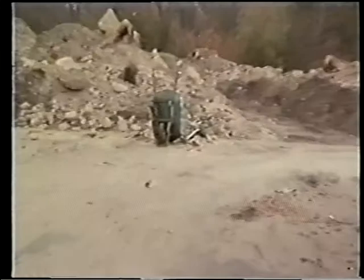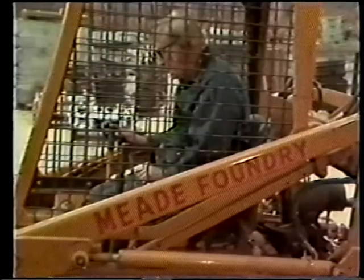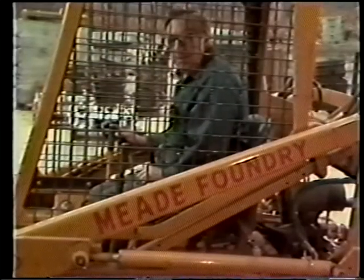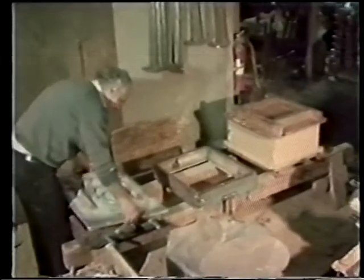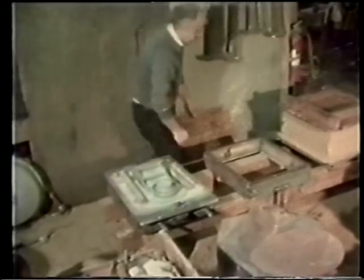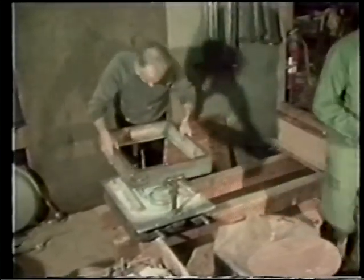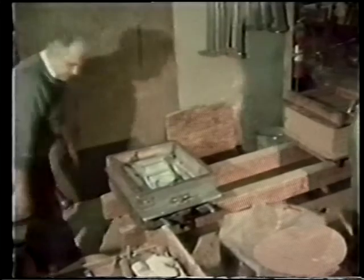Another type of casting frequently used in making aircraft engine components is sand casting. This involves using sand as the mold material. At the Mead Foundry in Bedford, Massachusetts, sand casting is done for a wide variety of parts. First, a pattern, along with forms for sprues and runners, is placed in a metal box made in two parts, so that each half of the mold can be produced separately. This allows the pattern to be removed. Talcum powder is sprinkled around the pattern to prevent sticking.